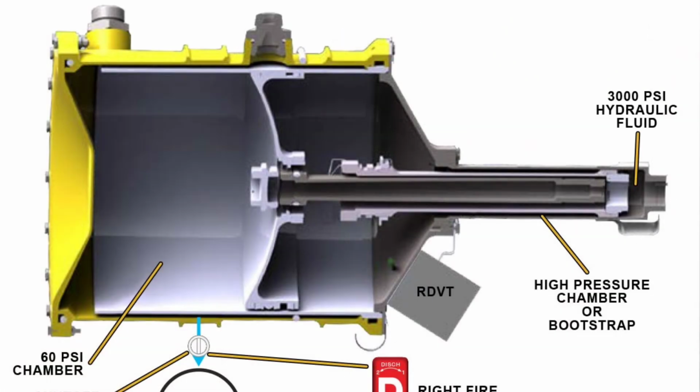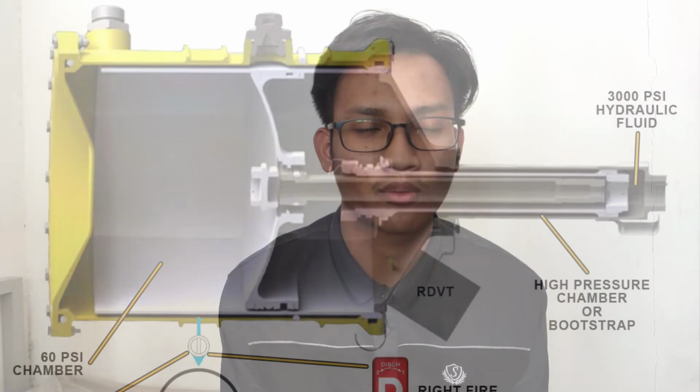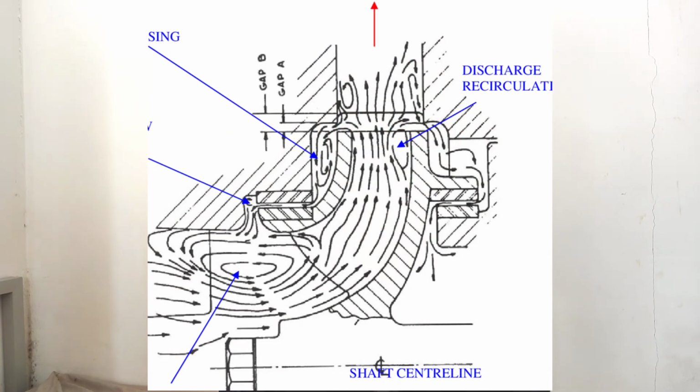Next, keep the reservoir clean. Rags, tools, and even cell phones can all find their way into the reservoir. When they do, they block the suction tube, creating extreme pressure and causing cavitation.